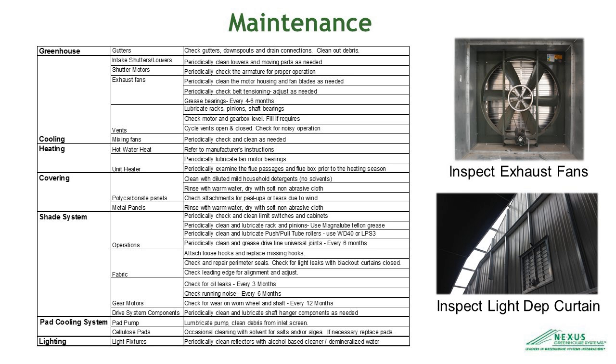Exhaust fan motors, you'll occasionally want to look at those, make sure that their belts are tight, and the motor's in alignment with the fan, and that all the bearings are greased. Your vents, make sure that all rack and pinions are greased on a regular basis and in alignment where they're supposed to be. Always listen for any kind of noises that sound like it might be buckling or needing some grease, but these are pretty regular routine that really don't take a whole lot of time. It just becomes part of your everyday operations.